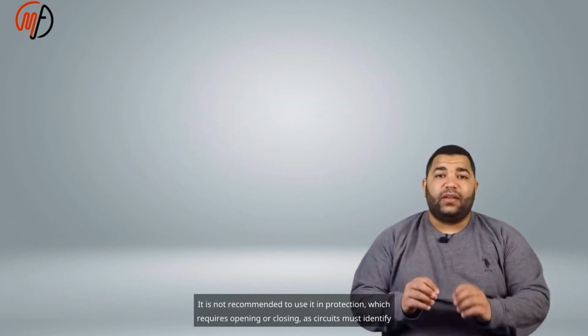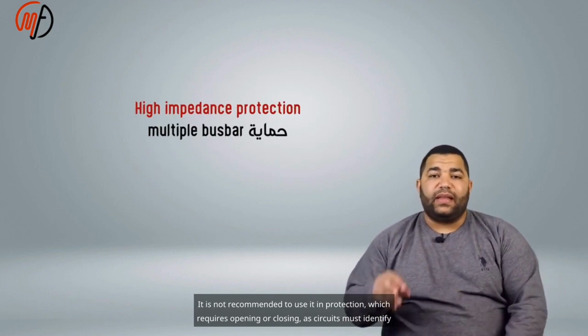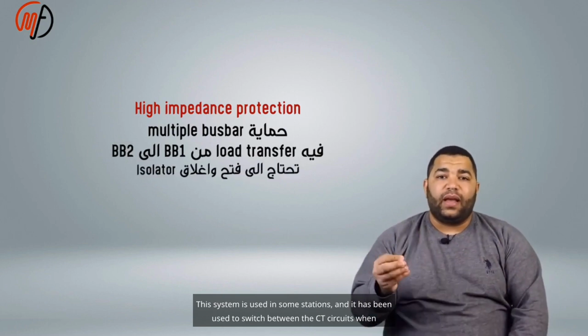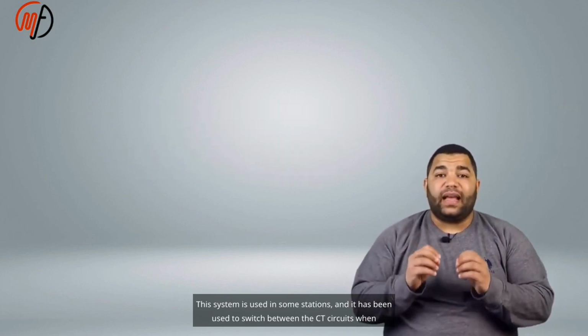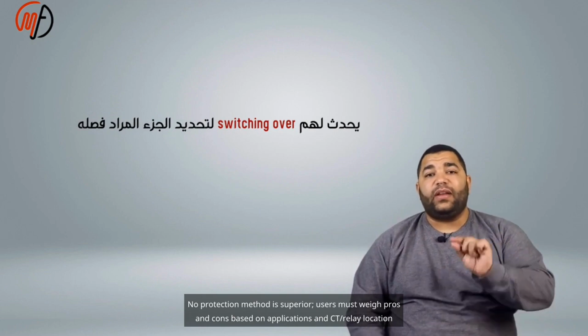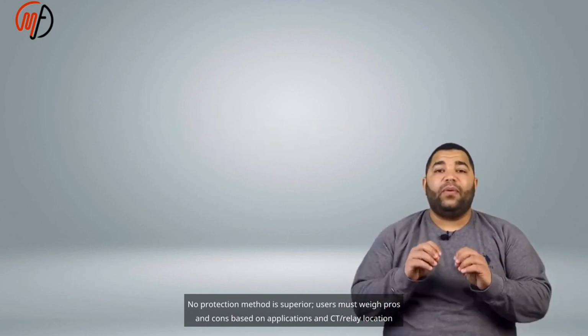It is not recommended to use it in protection which requires opening or closing, as circuits must identify the part that needs to be disconnected, whether it is during a fault or not. This system is used in some stations, and it has been used to switch between the CT circuits when transitioning from one protection method to another. No protection method is superior. Users must weigh pros and cons based on applications and CT relay location.